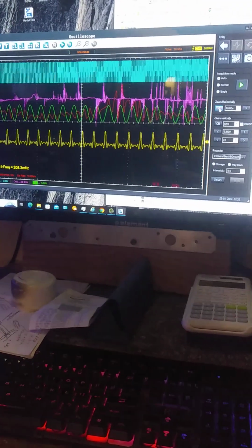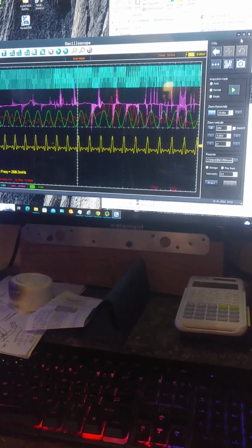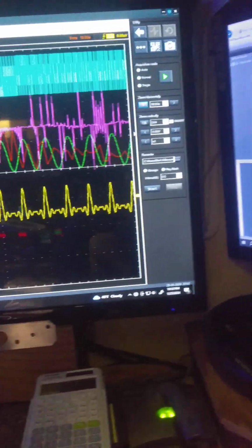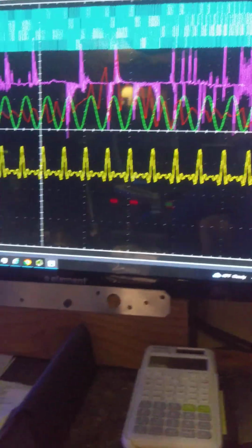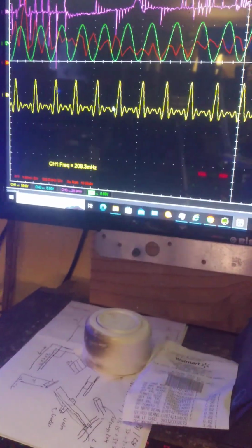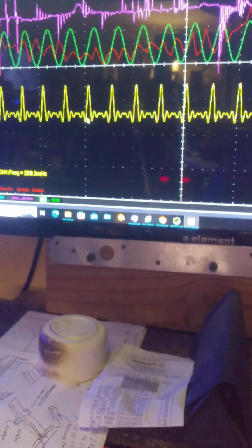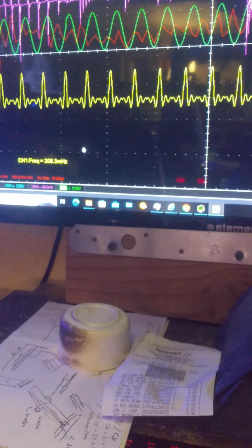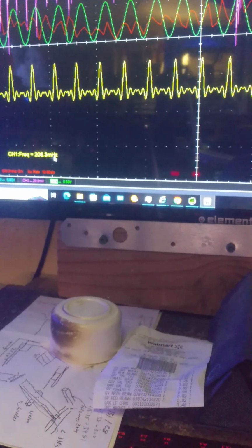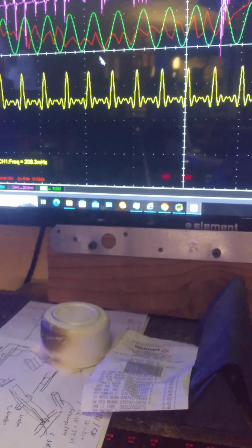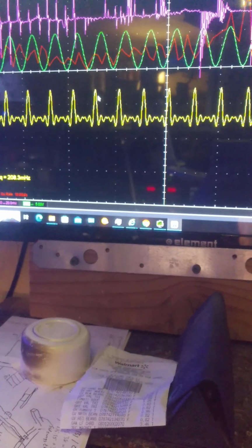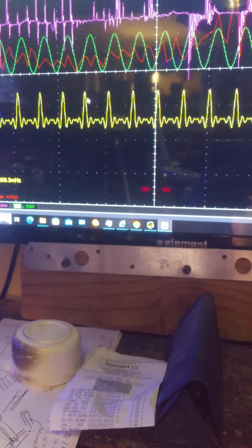And you can see the scope here. Let me try to get this expanded here. So you can see that I've got it set to 10 seconds per division, and here is the channel 1 frequency, which I think is the only thing, and again, I'm still learning how to use this thing too. I'm trying to determine if I want to keep it or not, but it's measuring 208 millihertz. But you can see the waveform is accurate, and the point of this video is to show you the pitfalls of aliasing, particularly on cheap scopes.